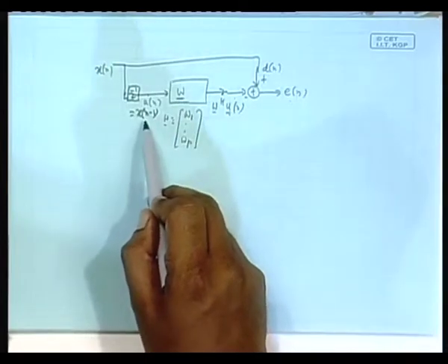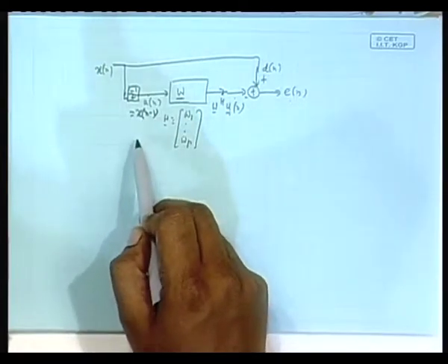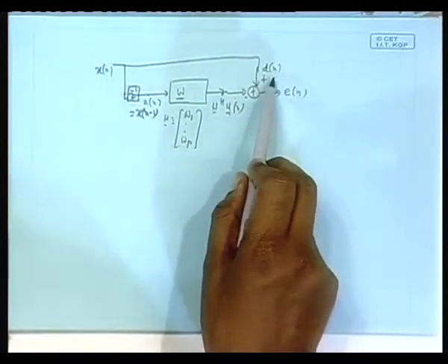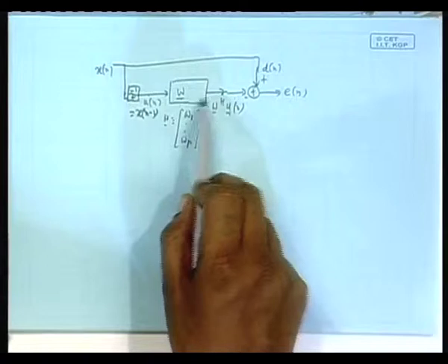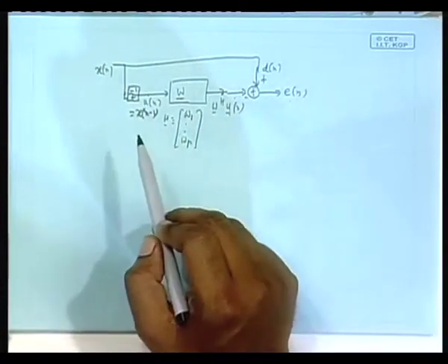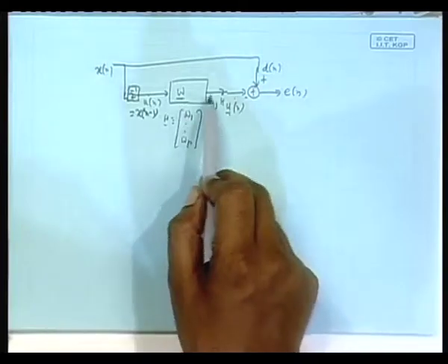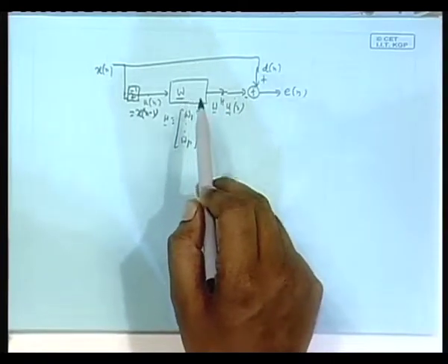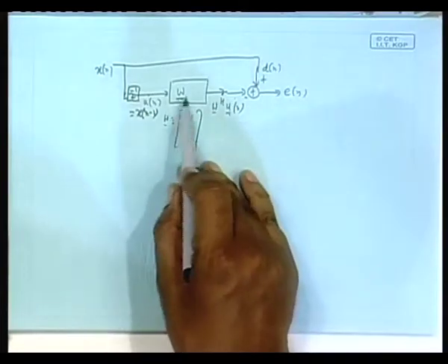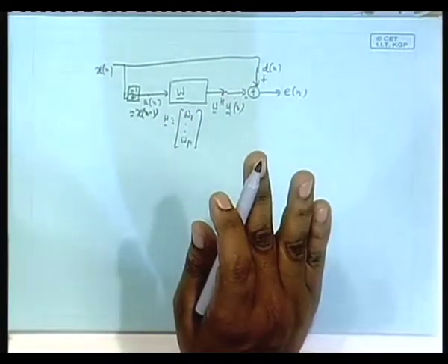Even though the random variables here, x n minus 1, x n minus 2 up to x n minus p, are all functions of n, and the thing that you are going to project, x n, also is a function of n, the combiner coefficients are independent of n. So whether at nth index or mth index or kth index, you get the same combiner coefficients. That comes from stationarity, which is beyond question now. That is why the combiner coefficients are independent of n.